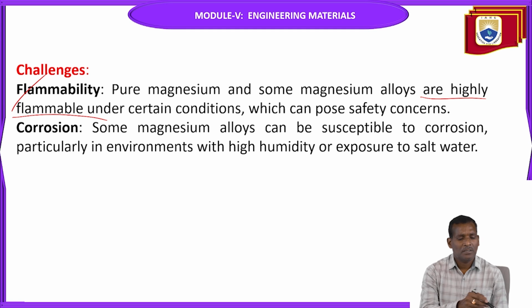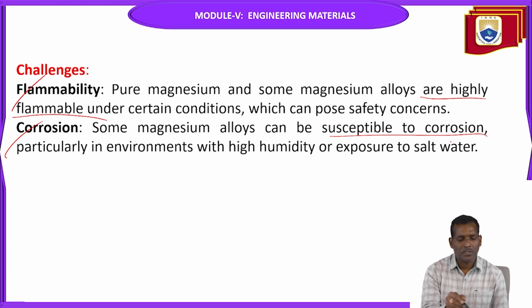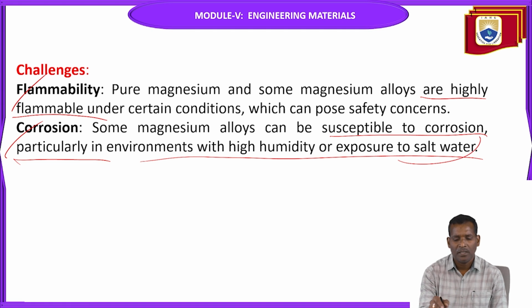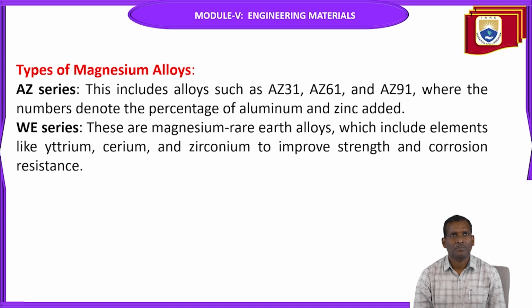And corrosion, some magnesium alloys can be susceptible to corrosion, particularly in environments with high humidity or exposure to salt water. Whenever this material is exposed to salt water, there will be corrosion. So these are very challenging parts. These two are related to magnesium alloy, flammability and corrosion.